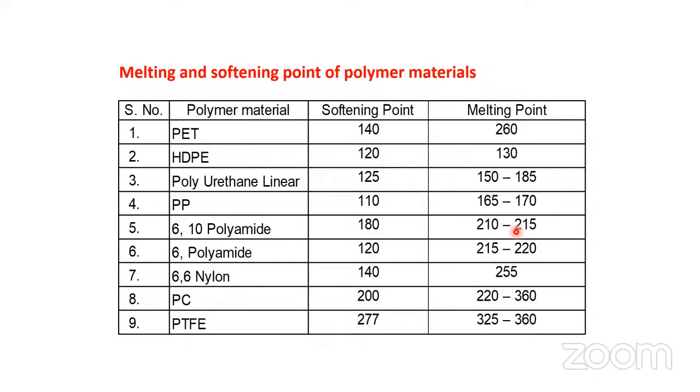But in this case, you will get a range of melting temperature, because this is the basic testing to get the melting point. Range means a start point and an end point. Yes. From this testing, you can't say this is the exact melting point of your polymer. This will always provide you the range.